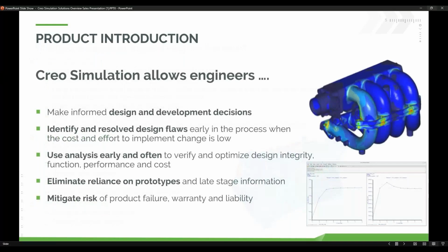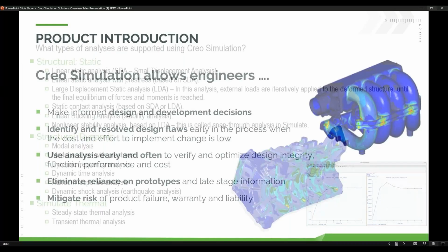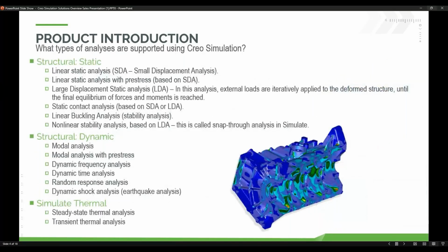One thing I will mention, the Simulate Thermal enables you to analyze those fields and heat flows. It does not calculate these conditions automatically. Simulate Thermal is not a CFD program. It is not a computational flow dynamics program. We do have a flow analysis program.